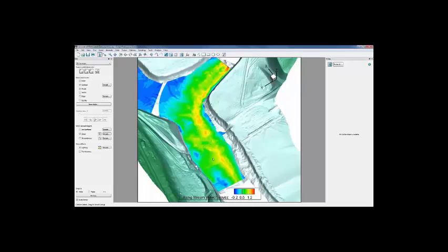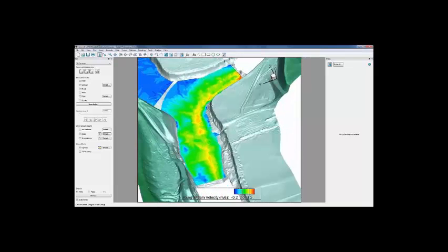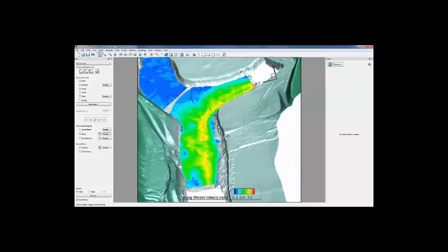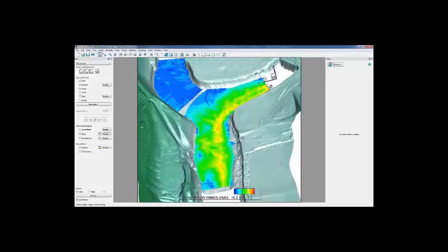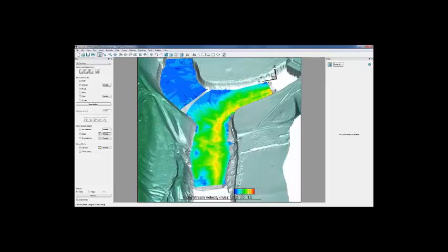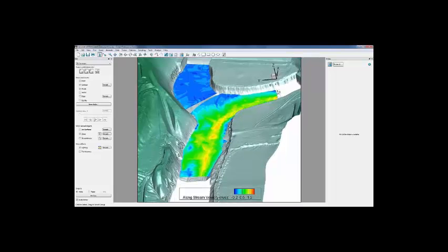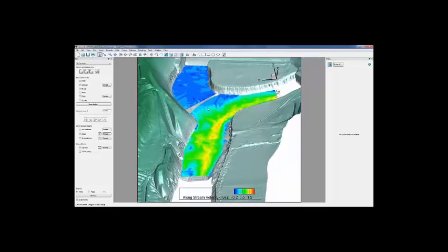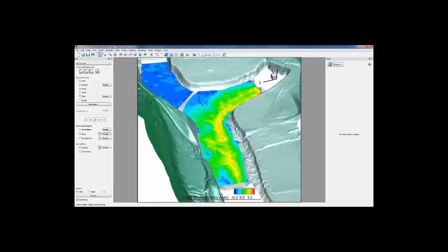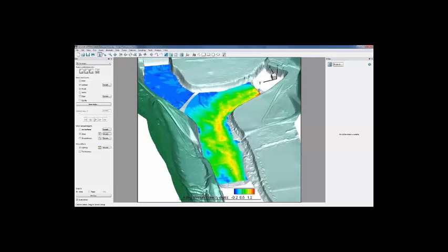velocity area. So these slices right here, as I'm planning a site like this, I can look at how does my velocity behave. Where do I have that strongest ratio? Where do I have something, again, maybe some change in the bathymetry that's going to affect this relation, and I won't get a good measure. There's other things that we can do.